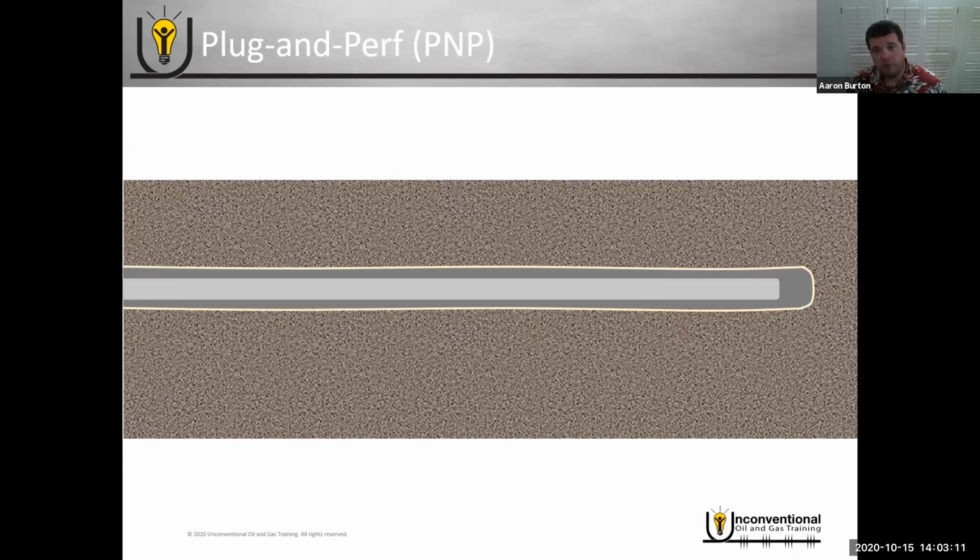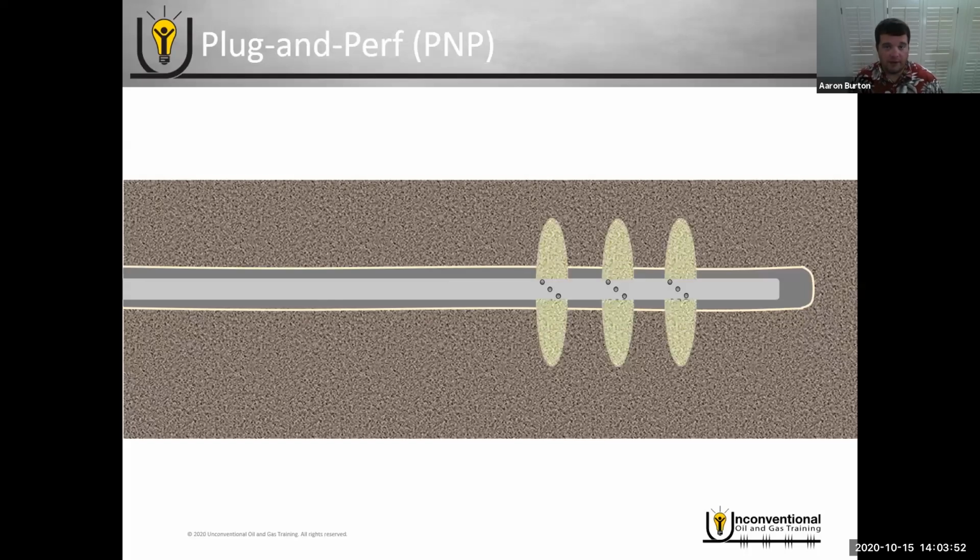Once we're ready to begin fracturing, we'll zoom into the toe here. Now, if you have this set up here where you just have a blank casing string and you've cemented it into place, you no longer have the ability to pump into your wellbore, into that target reservoir. So in this particular case, you're going to have through tubing intervention with coiled tubing or tubing conveyed perforating to be able to go in and perforate the well. So you perforate the first stage, those perforations will penetrate through the casing, through the cement, and into the target reservoir. And then once you've perforated your first stage, pull out of hole with your coiled tubing or your workover rig, and then you can begin your first stage frac job.